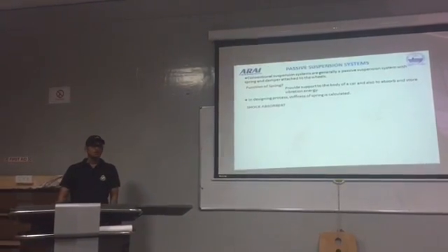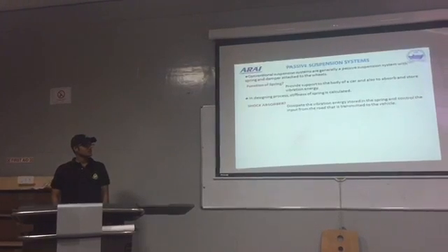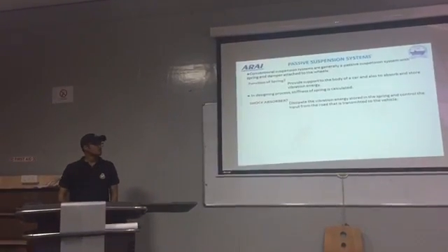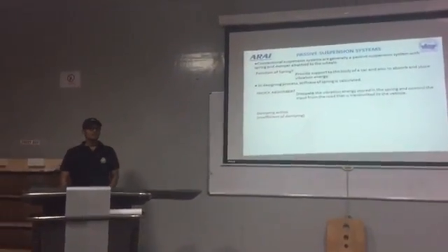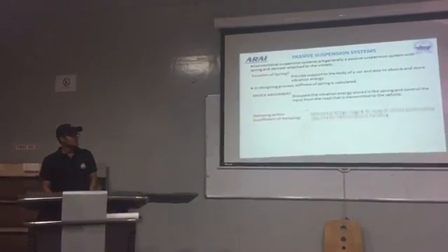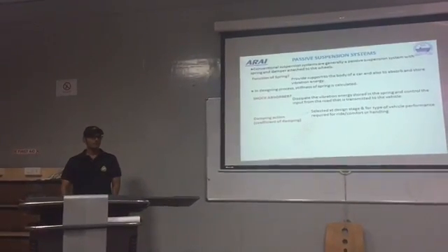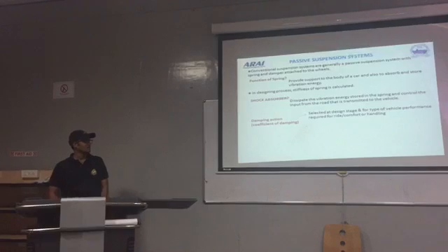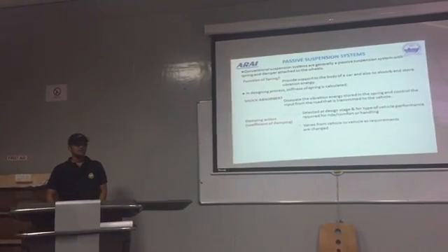Shock absorber. What is a shock absorber? It dissipates the vibration energy stored in the spring and controls the input from the road that is transmitted to the vehicle. The damping action is nothing but the coefficient of damping. It is selected at the design stage, and for the type of vehicle, it performs as required for ride comfort or handling. So it varies from vehicle to vehicle as requirements change.